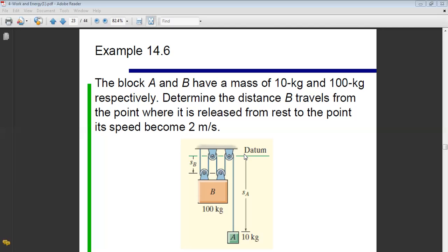Here, using the work and energy will simplify a lot the approach, okay? So instead of writing several equations, finding acceleration, then using relation between acceleration and velocity, we can obtain velocity by just writing the principle of work and energy. But also we should pay attention that we still need to use the formulas for pulleys. So we should write the total length of the cord and relate the motion of A to motion of B. Okay, so here let us start by relating motion of A to B.